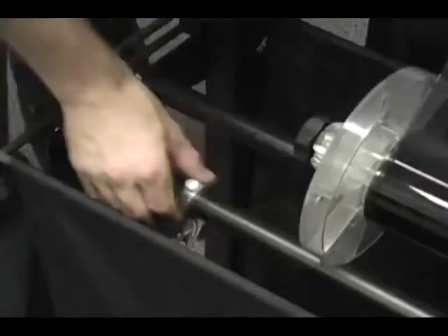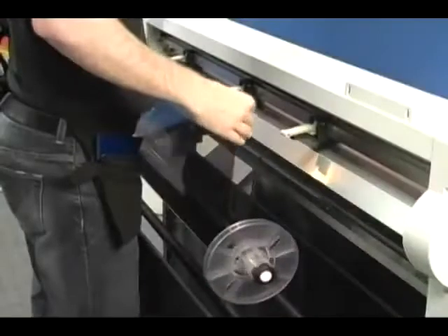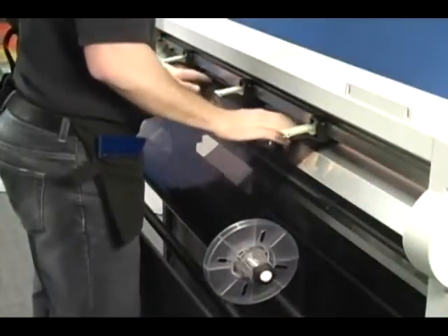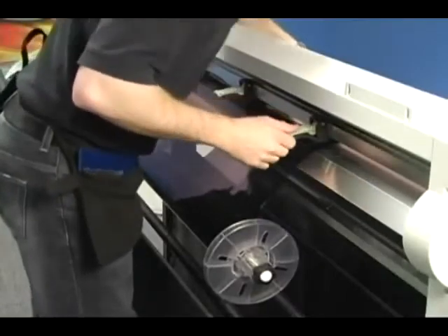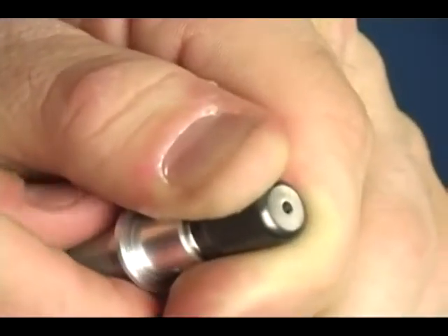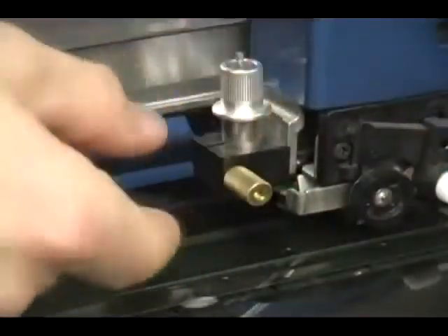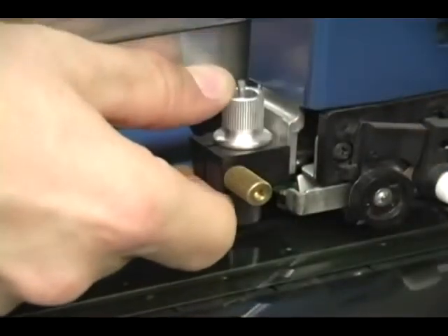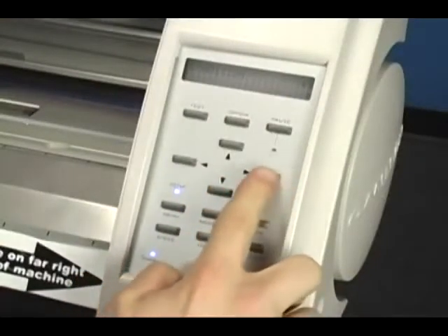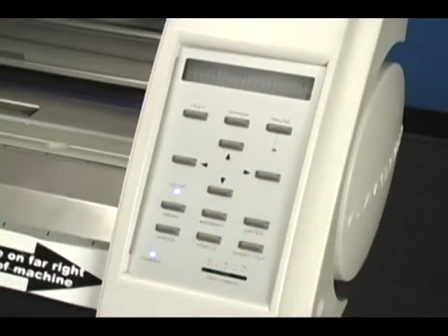The first thing you need to do is load the window film into the cutter. Next, you'll set up your GX400. Lock down the pinch roll wheels. Then set the 25-degree blade in the blade holder. Set the blade extension to the thickness of the film. The GX400 control panel is easy to navigate and offers a variety of setting options.